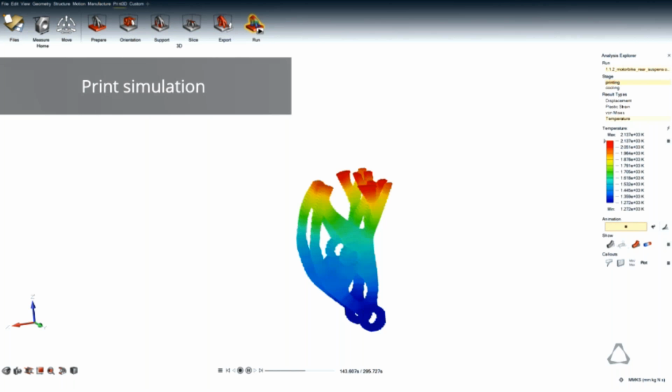So though it may be organic in shape, it may not make sense. You can see there are overhangs. There are areas where the typical rule, and this is just a guidance rule, is 45-degree overhangs for metal additive before you need support. So anything over 45 degrees will then need support material added, and that support material will then need to later be removed. So there are design softwares that will allow for build orientation and design the part properly based on that orientation, to reduce, or if not completely eliminate, the amount of support needed to build that part.